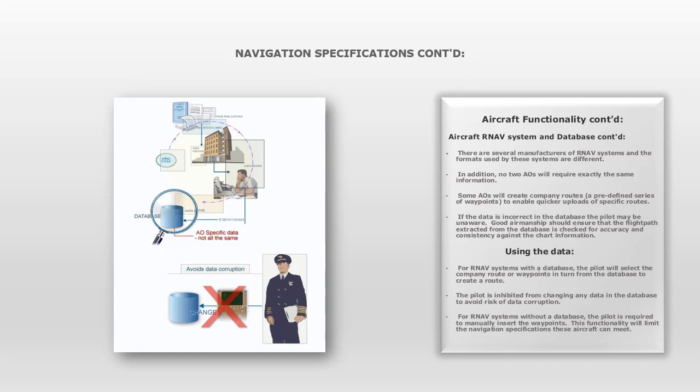The pilot is inhibited from changing any data in the database to avoid risk of data corruption. For RNAV systems without a database, the pilot is required to manually insert the waypoints. This functionality will limit the navigation specifications these aircraft can meet.